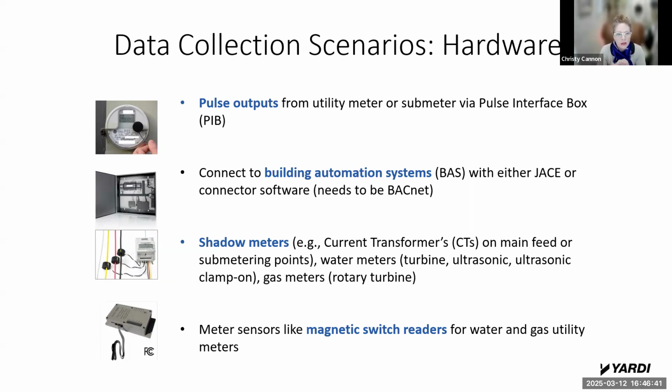That sort of thing is what we see a lot. And there are things like ultrasonic clamp-on water meters that we do use in situations like that. They're expensive, like $6,000, but cheaper than replumbing. One of the first places we used it, the plumber actually quoted $100,000 to replumb. So $5,000-6,000 compared to $100,000 is kind of a no-brainer.